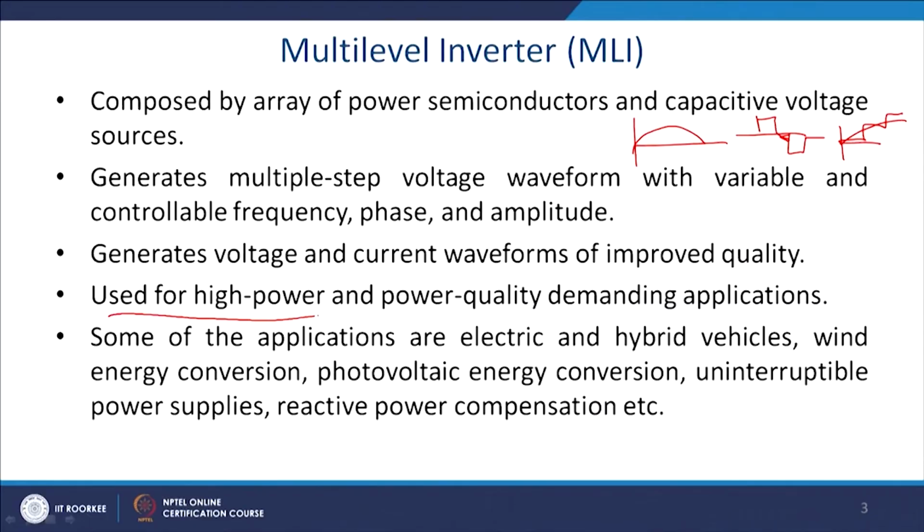Since the cost of power electronics devices goes high with the rating, we need to increase the power handling capability by connecting devices in series. For this reason it is used for high power and high quality power management applications, and it is one of the basic needs for our FACTS devices.